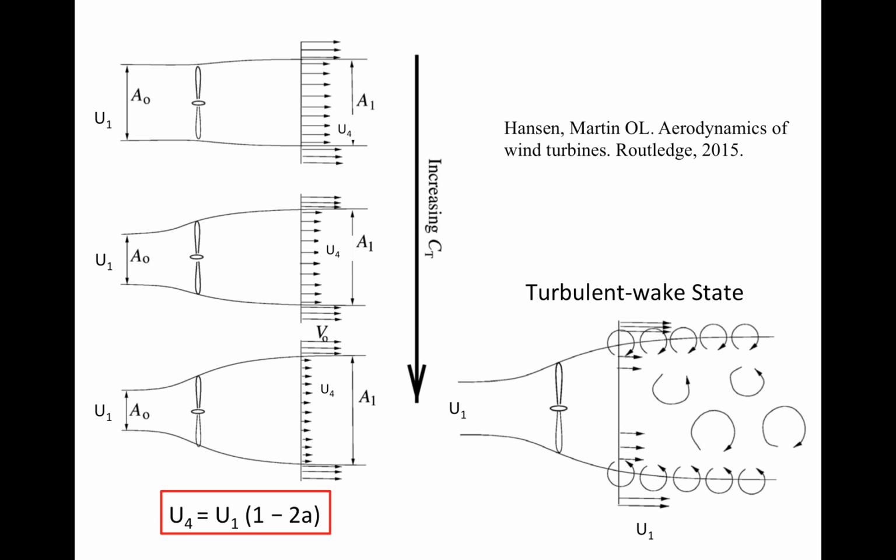The reason is that the actuator disk model is based upon a scenario where there's no momentum transfer in and out of the stream tube. The stream tube itself is a control volume, isolated from outside. But now you have momentum transfer, and the wind is flowing into the stream tube. So it has broken the basic assumptions of the